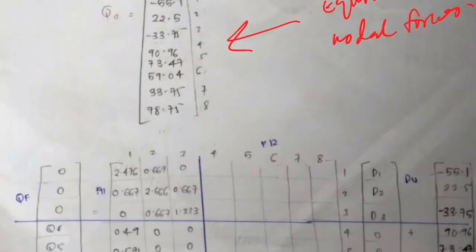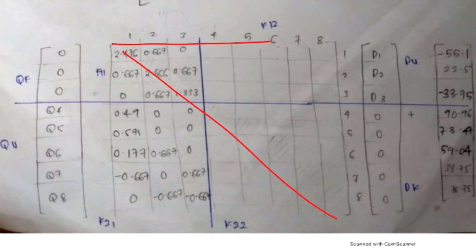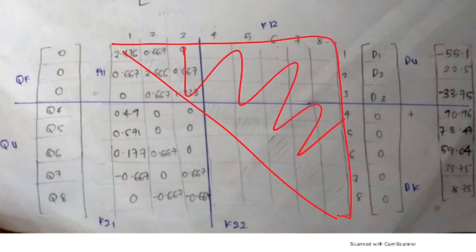So this is all. This is the stiffness equation for the truss. For the beam, in full. As I mentioned, this is unnecessary unless the question asks you to do so. If the question asks you to give the stiffness equation, you need to give it in full. In full means like this. You must fill in like this, fill in with value, because the matrix is symmetric.